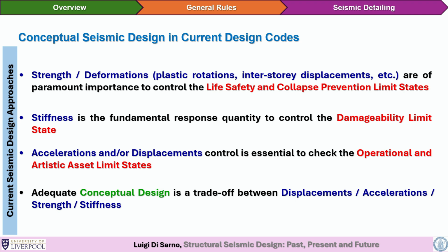Acceleration is something that is not really yet in the DNA of the engineers. What does it mean? We want to create functionality. Those of you that have already designed tall buildings know that this is a fundamental governing design parameter, a problem for high-rise buildings. It is not always the case for buildings, where we look only at the story drift, for example, or at the story shear. Acceleration will create the comfortability of the building.